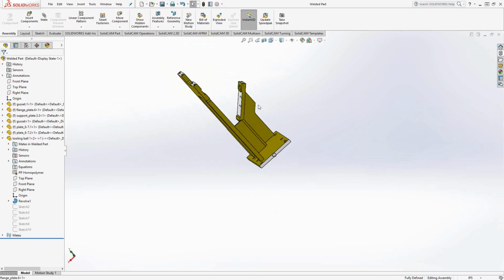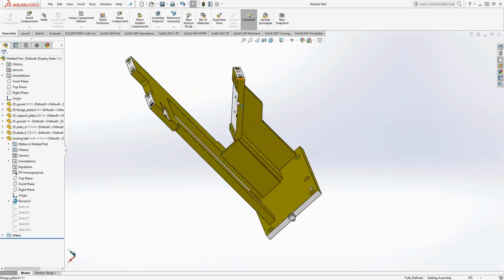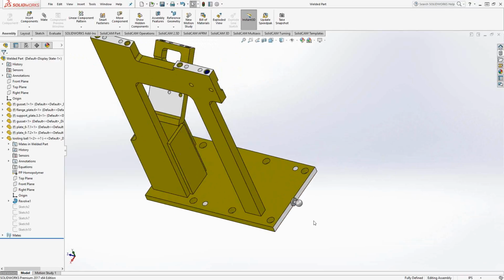So now, this thing would be sitting on a fixture plate at a certain angle. Hopefully you have the print that says what angle it's at, and you need to machine this face up here. Now, seeing as nothing on here is a true face, you can't really touch off on anything in here and know that you have your actual heights and all that. So we're going to use a tool ball for that. This face right here, let's say that it has already been machined. We know that is true, so the ball is sitting true. We're going to use the ball to set up our coordinate systems.